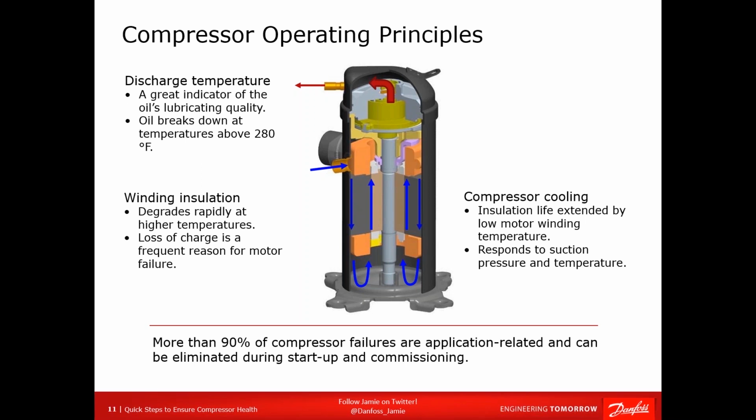In this case, it's a scroll. So it's going to enter into the outside of the scroll wrap. It's going to get pushed towards the center, up and out at high pressure and temperature. So the more heat the motor has compared to how much refrigerant vapor is coming in, combined with the temperature of that vapor coming in, determines how hot the vapor is going to be when it finally enters into the